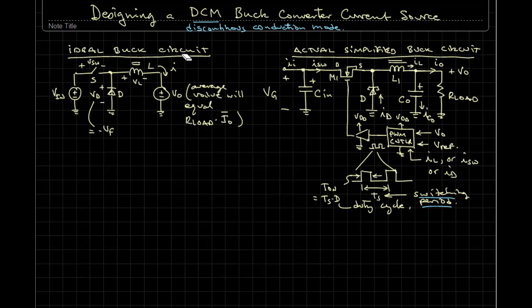Notice that I_L, in the simple form, I_L and I_O are the same thing. But we do notice that ultimately in a real circuit, the I_O is really the current that's flowing out of the buck converter that includes a large filtering capacitor and is flowing to the load. We see that right here.